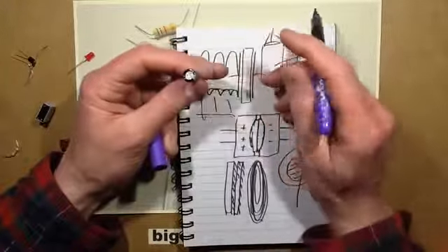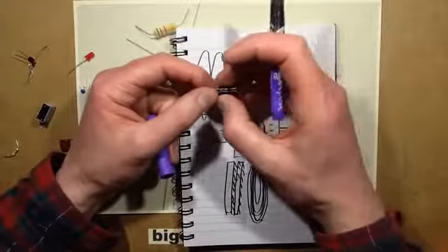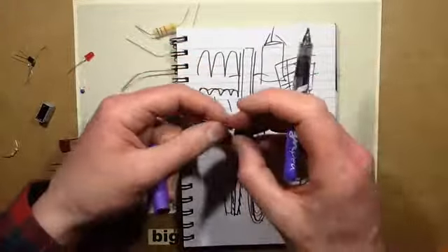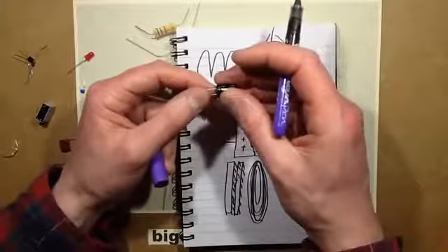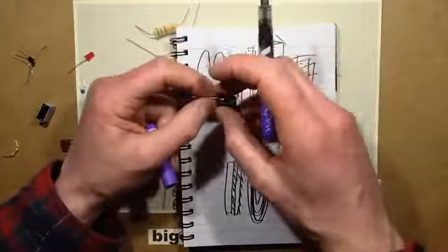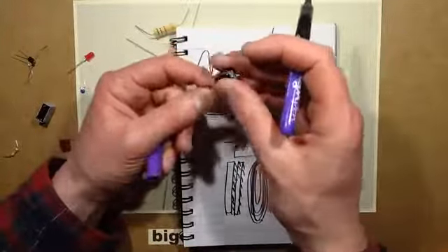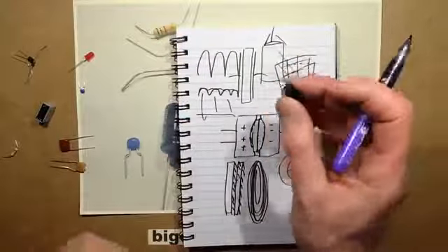And the other option there, if it doesn't do that, is sometimes it blows the whole can off, and it just makes a mess. It gives out a vapour of the electrolyte, which is slightly caustic. It can unravel the foil across the room. It can go off with enough force to actually cause injury if it hits you. So you have to be kind of careful with electrolytic capacitors.